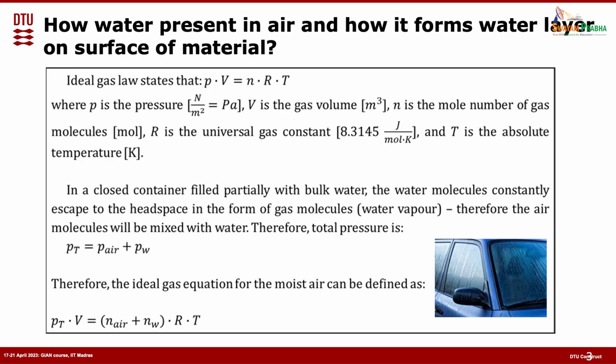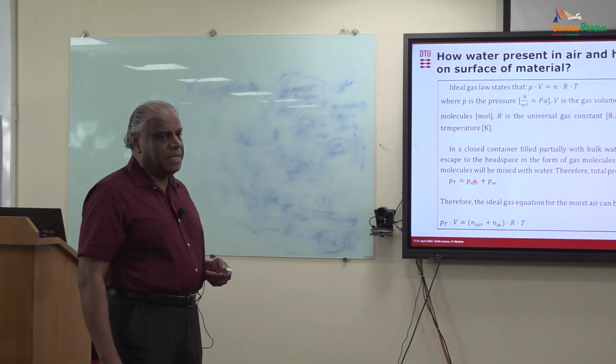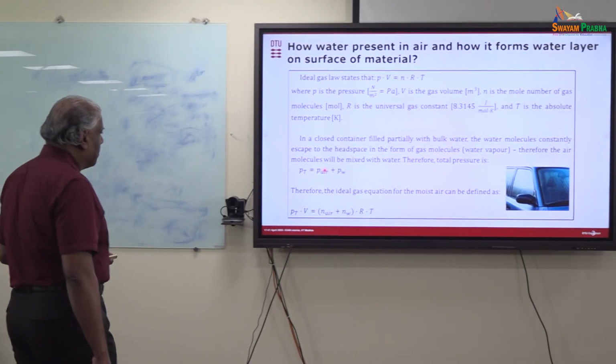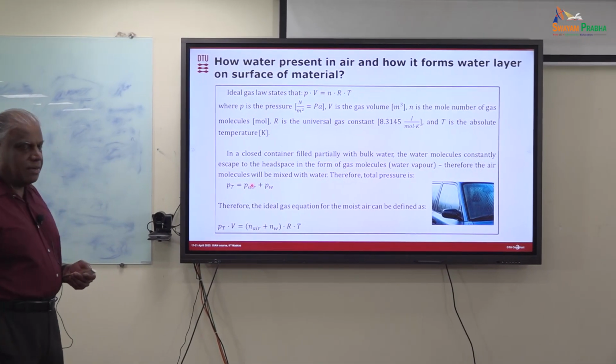So, elaborating a little on that, most of the time atmospheric corrosion is the biggest problem. Although there is corrosion in fully immersed conditions, characteristically fully immersed corrosion is much more possible to predict compared to atmospheric corrosion. Atmospheric corrosion occurs because one of the key things related to it is the moisture in the air.